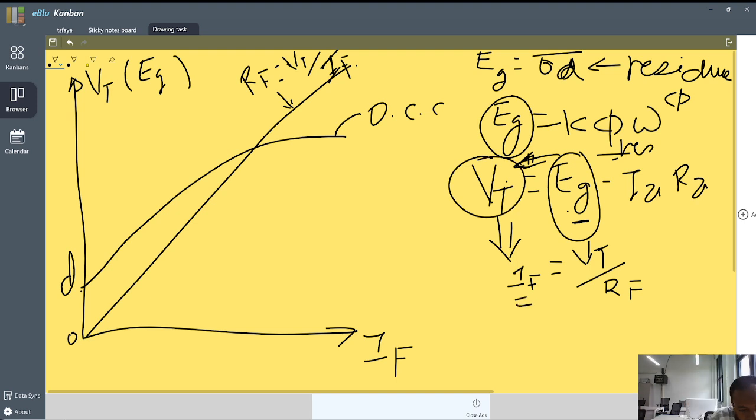How much? For example, this is an IF curve. To produce a smaller amount, we can say this is maybe IF1. It produces a smaller IF. What is the consequence of IF? If IF is increased inside the machine, this IF will produce an additional flux inside the machine.